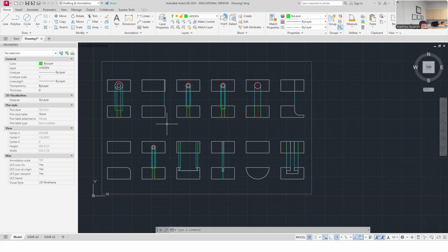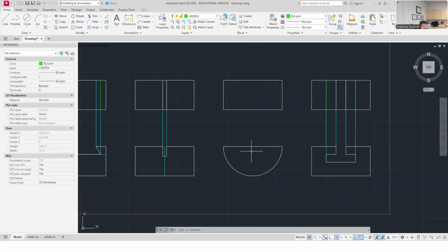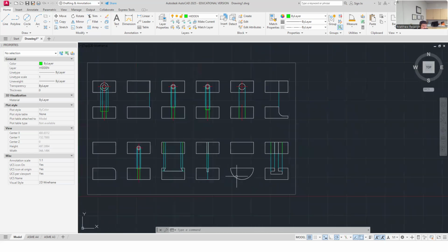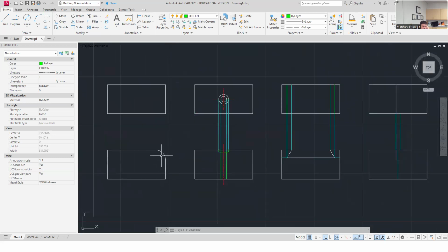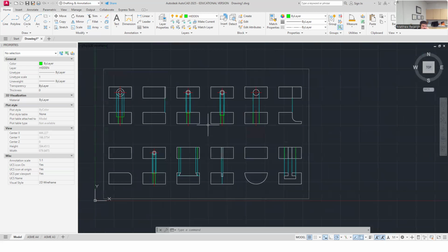Kind of interesting. Remember, center lines really are associated with round features. It could be argued that maybe this would have a center mark on it, but I didn't put it on it, so I'm not going to hold you accountable. I mean, technically, we don't usually put center marks on just a standalone round or a fillet, but sometimes we do. But generally not. I think these would be fine left, and even on this inside fillet.